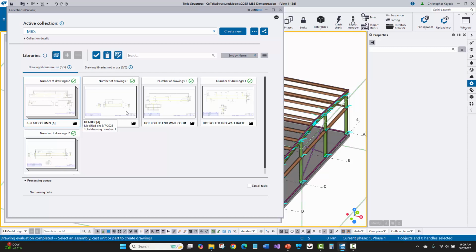that you're trying to train Tekla to take drawings that you've already cleaned up before across multiple jobs, store that collection out in the cloud, and then what'll happen is on future jobs, that cloud storage will then compare against the properties of different assemblies in your current model, and it'll try to automatically identify and map which drawings you've cleaned up in the cloud with which pieces that you're trying to make drawings of in the model, and automatically smart create and clone from that.